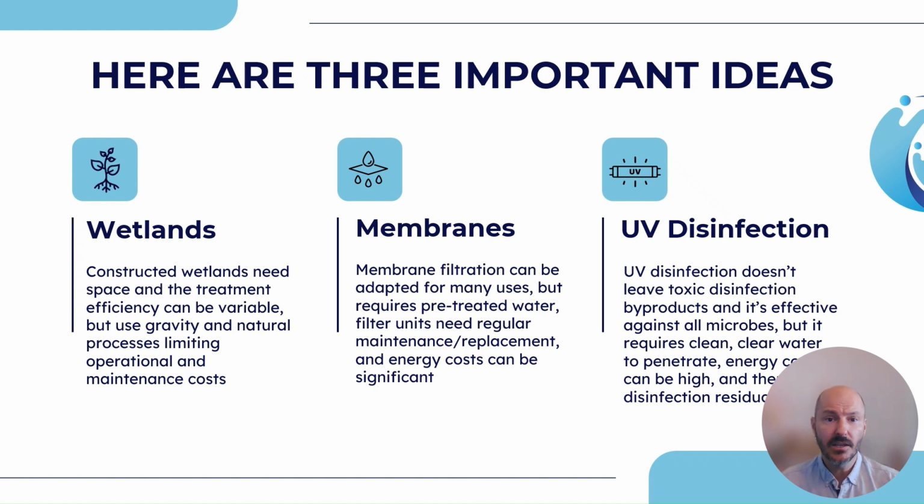And finally, UV disinfection doesn't leave toxic disinfection byproducts, and it's effective against all microbes, but it requires clean, clear water to penetrate, the energy cost can be high, and there's no disinfection residual.